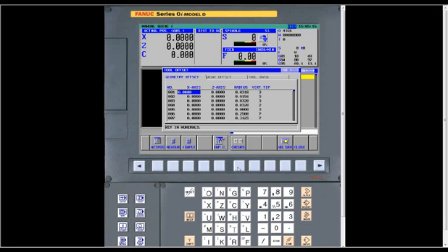All right. Question here. When you touch off the tools, normally do you have to input them again, or will the iGuide pull them into the setup? Oh, yes, yes. Because this is the same data that's on the CNC side. It shares that information. When you measure a tool, it will pick up the data from your standard tool offset screen.